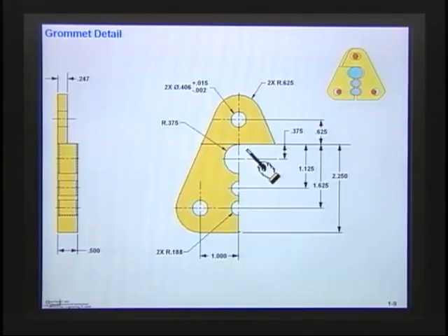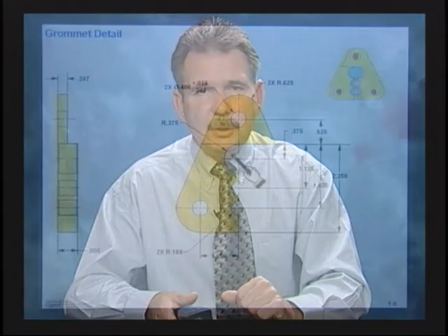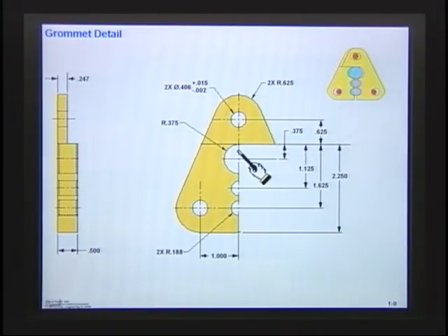At least initially, I'm just going to have you apply the datums first. Select the datums where you think they should be for these two parts going together. Once you select the datums, apply any perpendicularity or parallelism or form to relate the datum features. And then at that point, just stop.